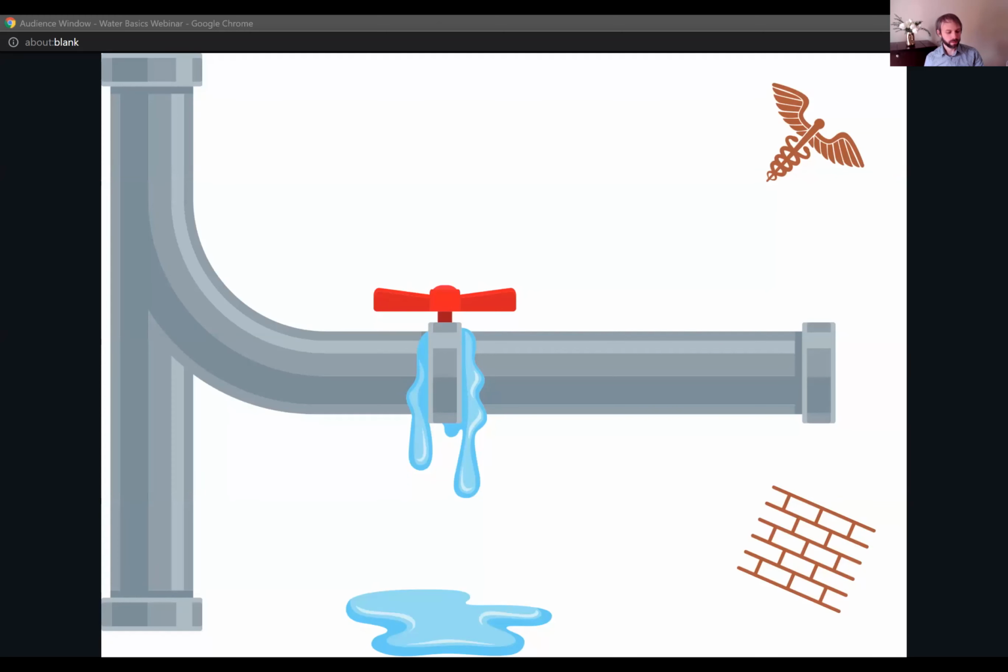Next up on our list of water uses is actually leaks. So not unintentional water usage. And these are a big issue, not just for wasting water, but you've got the health logo and the durability logo there. You've got rotting walls, rotting floors, rotting ceilings when you've got leaks. And then once they start rotting, they start to gather mold and mildew, causing all sorts of health issues. So it's a huge win for three different pillars if you can resolve water leaks and test for them and make sure that they're not occurring in a project when you're doing a project.